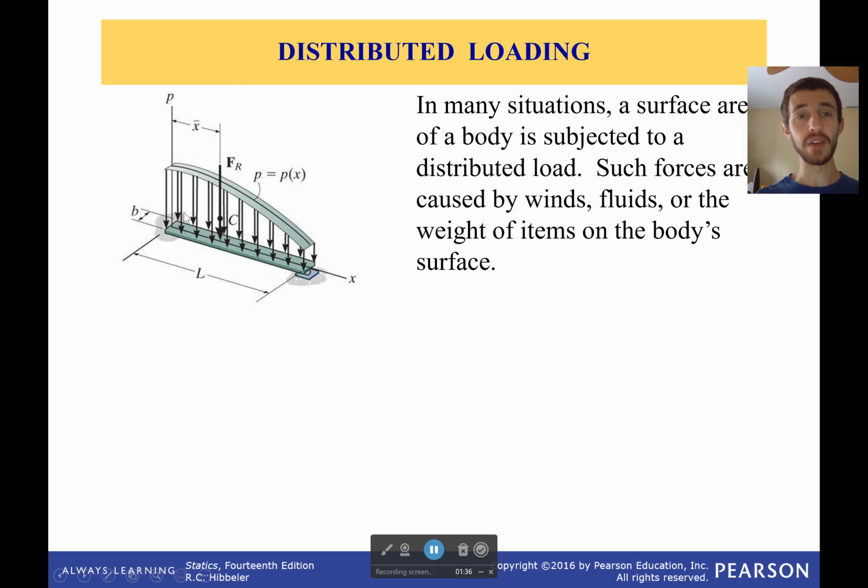All these things we've been seeing right here, where you have a bunch of arrows with a line connecting them, is something called a distributed loading, because in many cases the force isn't really at a single point, it's at a long series of points. It's just spread out over the entire thing. If you're carrying a big box, you feel the weight of that box all the way across your arm that's holding the box. You don't just feel it at one magical point at the center of gravity of the box. So these can be caused by fluids, they can be caused by the wind, they can just be caused because things have size. Most things in life are a pressure, they're not a force, so they're distributed.